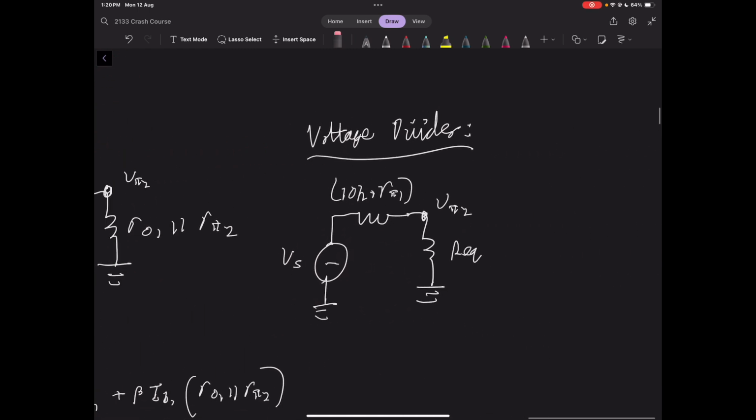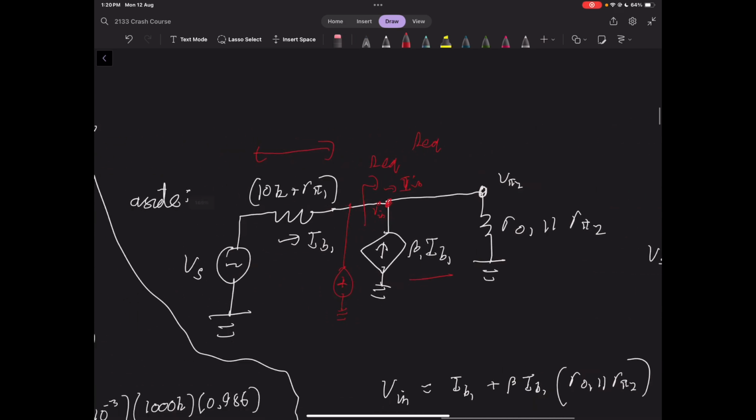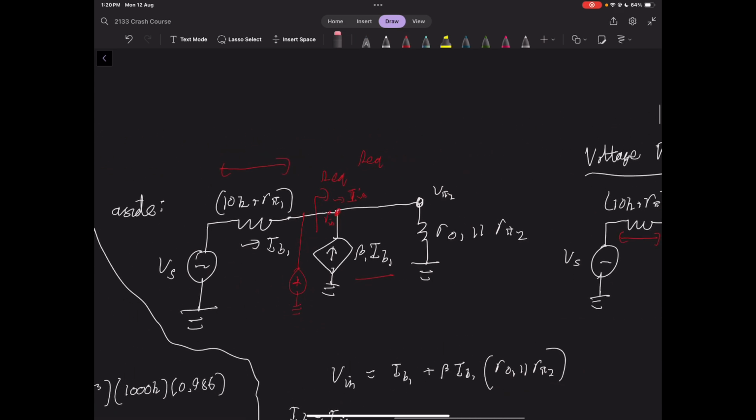So this is essentially the circuit that we're trying to make, right? We have our voltage source, we put these two resistors in parallel, and then we look in from that terminal there and we replace it with a resistor to ground, and then we can find V pi 2. So to find the equivalent resistance from this point, you do not need to draw in this left part of the circuit here. I've just drawn it in to try and make this point really clear because we're going to be using this a lot throughout this exam. So I want to make sure that that's quite clear.